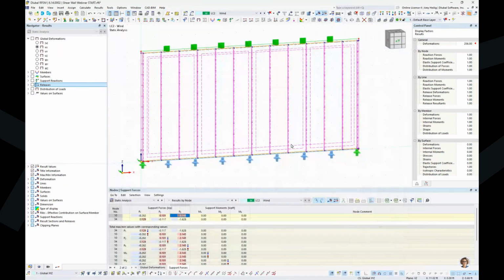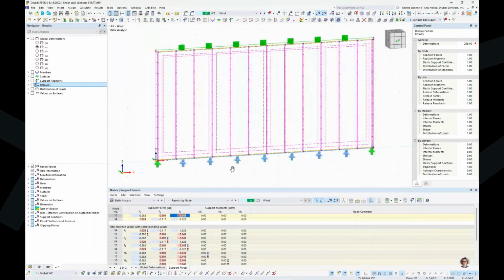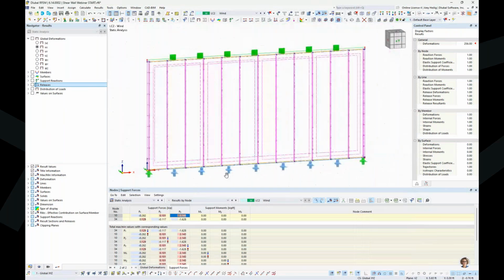So we can input all this information for our vertical members. Now for my horizontal top and bottom plate, I'm not concerned with buckling here. We likely have floor framing in addition, and the bottom plate here is going to be connected directly to our foundation. So buckling is not so much a concern. So we can simply not assign an effective length to those members.